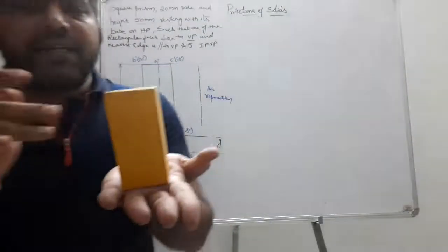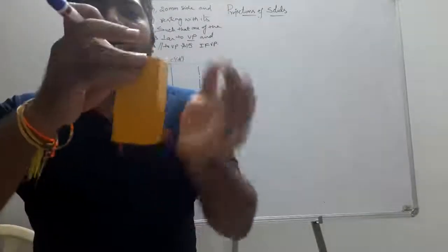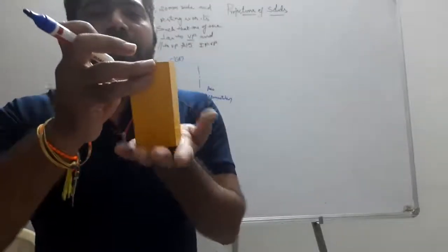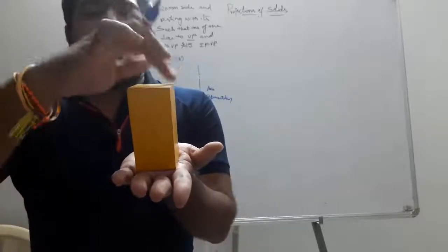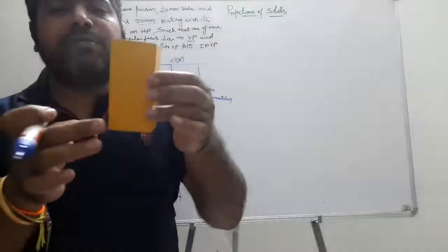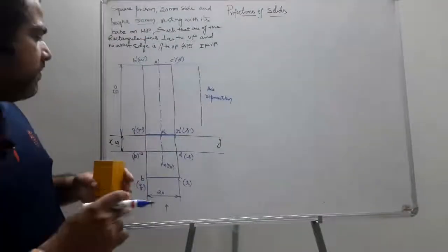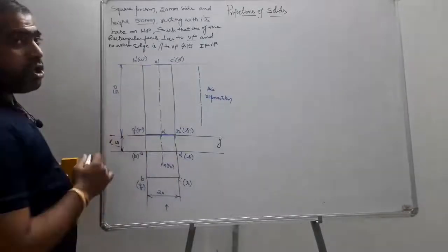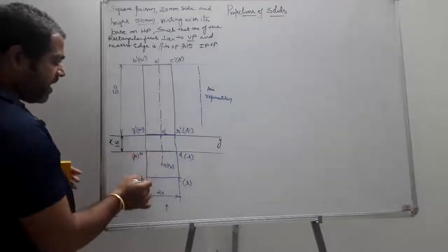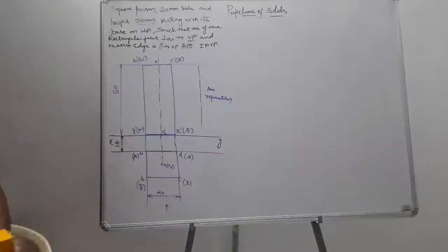Okay, so in this rectangle, while you are going to see from the front, here you obtain 4 points, here you obtain 4 points. If you see from the front, B comes behind A, C comes behind D. Similarly, Q comes behind P, R behind S. So the front view is going to be marked with dashes. The front view points are considered as B dash behind A dash, C dash behind D dash on the top base, and Q dash behind P dash and R dash behind S dash in the bottom base. Okay? Okay, students?